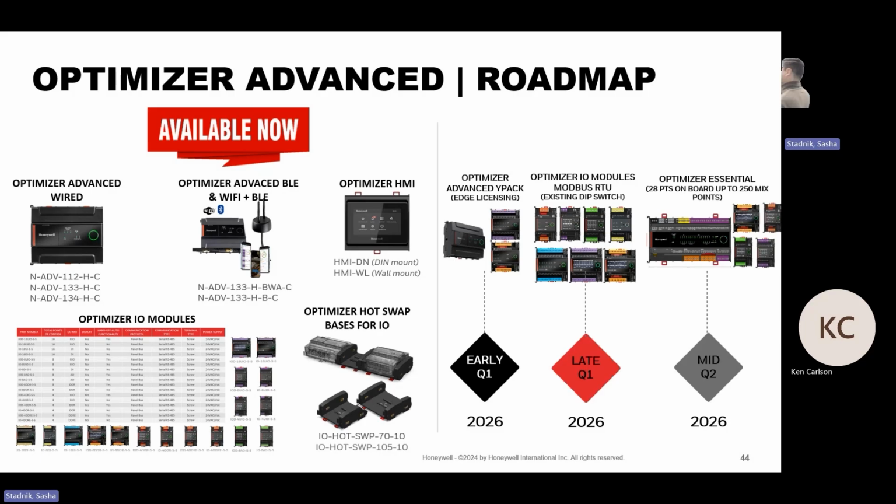What is the problem of the edge? At that licensing piece, the real problem is that you can only have 3 drivers per controller on the portability licensing of Niagara. Those drivers are the protocols. So manufacturers like us need to choose: BACnet, Modbus, Panel Bus, and what type of feature is going to be added on that edge licensing.